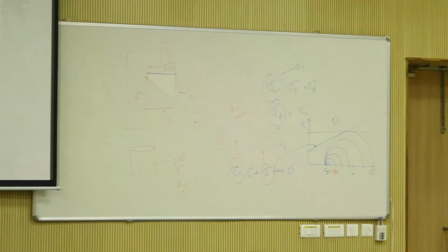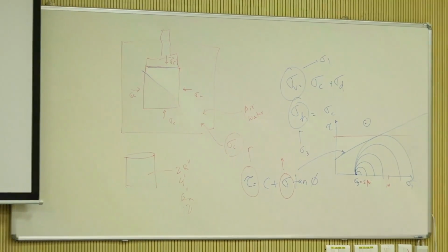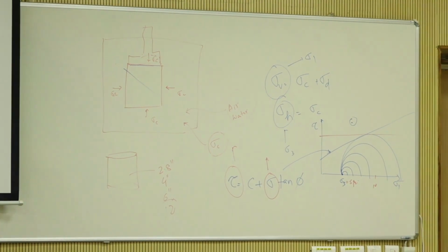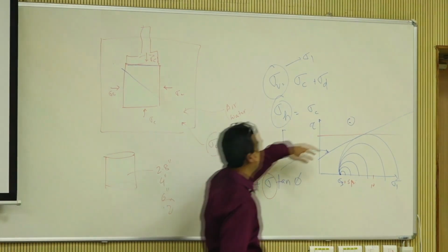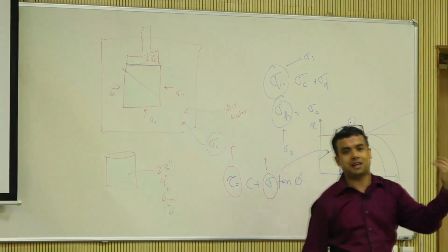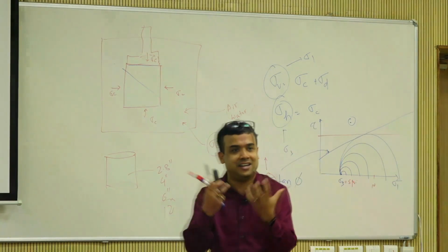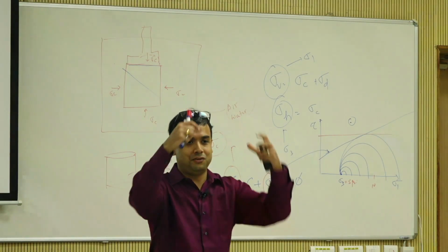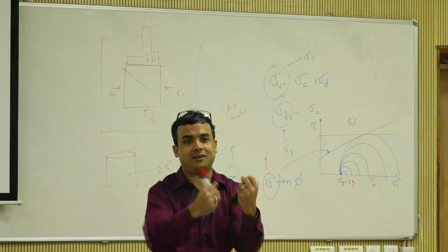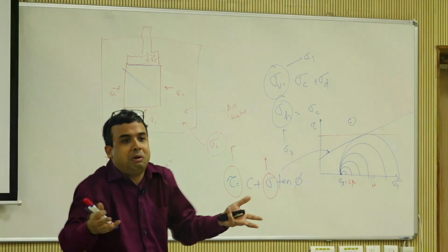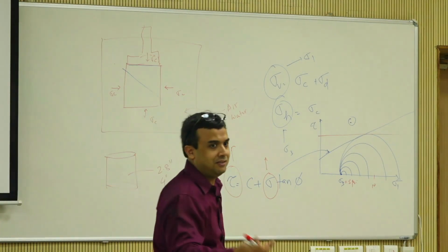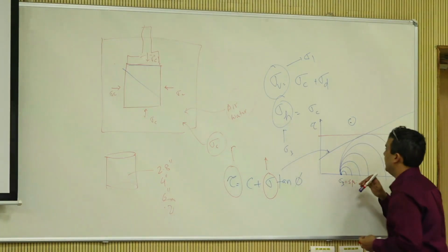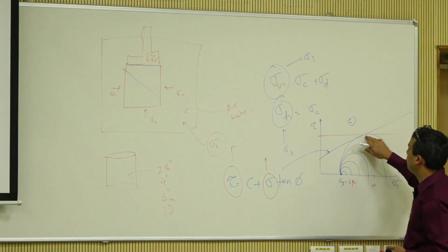You said something. Yes, when you have 100% saturation, then what you are trying to still work on is the total stress. What will happen is all the stresses are actually taken by water. So if you do it undrained, when you apply additional loading, all of the loading is taken by water, so you're not gaining any strength. That's what happened, right? Consolidated, undrained and stuff like that. So you'll see those behaviors sometimes.